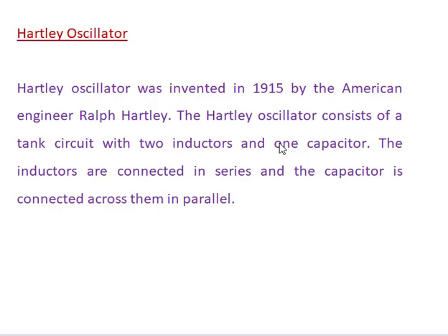Here, the Hartley oscillator also consists of a tank circuit. The tank circuit consists of two inductor coils and single capacitor. The inductor coil and the capacitors are connected. The two inductors are connected in series and the inductor and capacitor are connected in parallel.